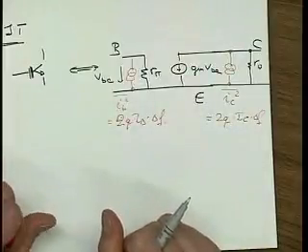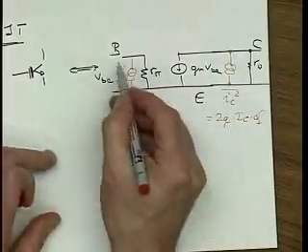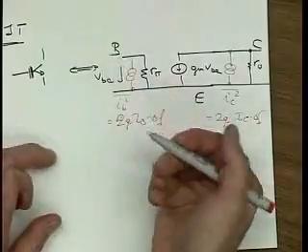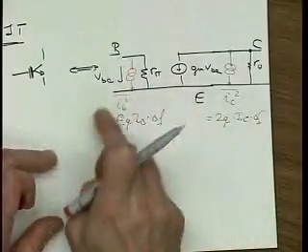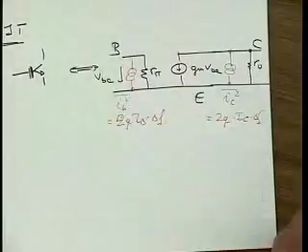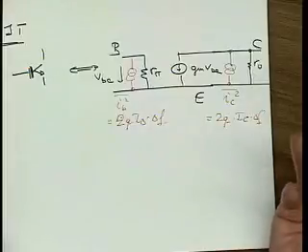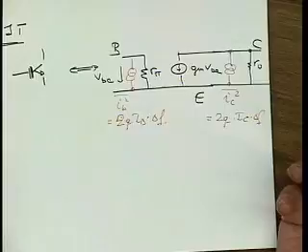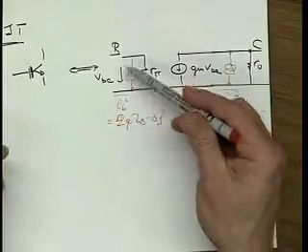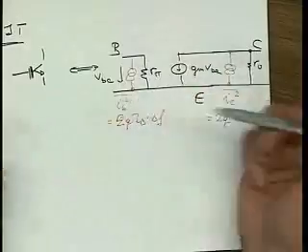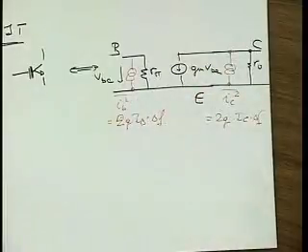In bipolar transistors, one thing I should say is that this IB corresponds to the gate leakage noise current of a MOSFET, and presently, at least in MOSFETs, that contribution is still negligible. MOSFETs have an advantage there: this noise source just isn't present or not really relevant.